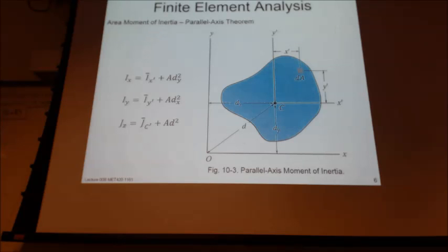What are we saying when we're talking about parallel axis? We're saying that if we know the moment of inertia of our main axis, then we can determine the moment of inertia at our parallel axis, or moment about that parallel axis. And x and y are the rectangular equations, J is the polar equation. So this should be familiar stuff that you're used to seeing from many moons ago, yes?